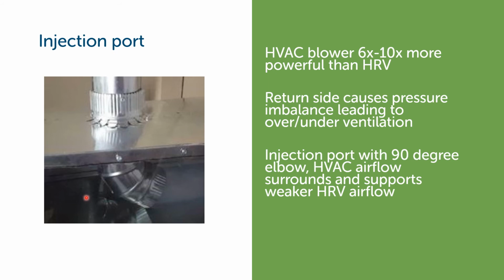In the past, and presently, installers are putting the supply air from the HRV into the return side trunk. And Bruce Manclark takes exception to that, saying that he thinks that's leading to overventilation, that there's so much suction on the return side of that main trunk that we're pulling way more air than we need to through the HRV, and we're creating overventilation.